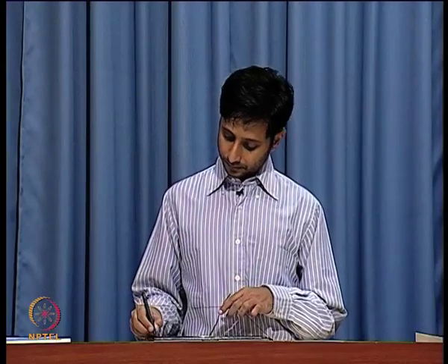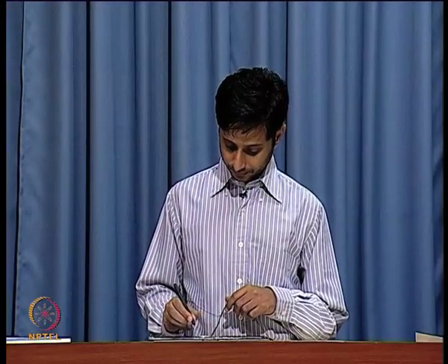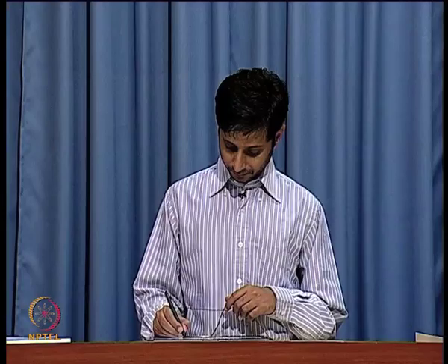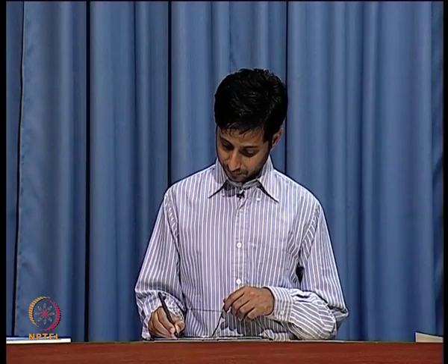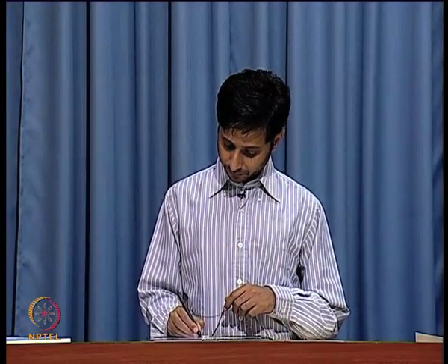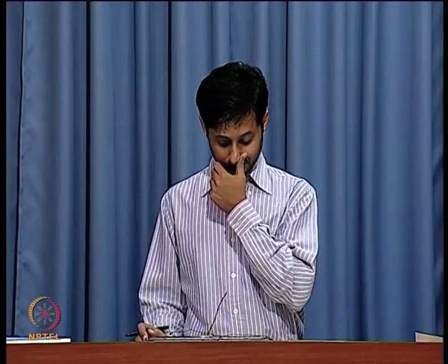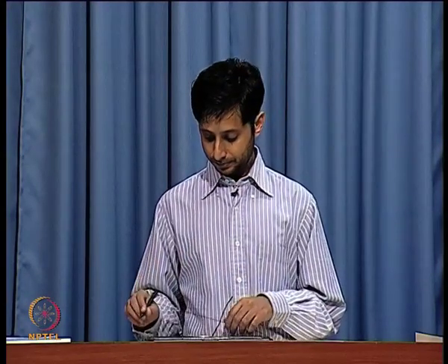If the junction is more reverse biased, D junction is going to become larger. That is basically the idea, right. Same formula applies for both source to body and drain to body capacitance. So, these two are called the junction capacitances, right.